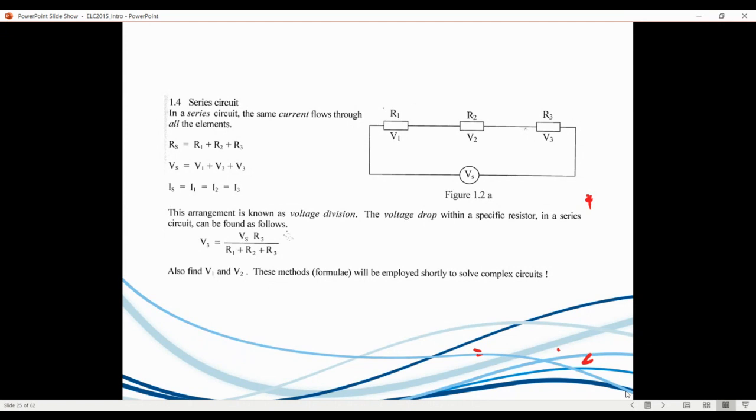For instance, if you have a source voltage there, and then of course that is supplying a current through those resistors. And if you quickly want to find the voltage across whichever individual resistor, you have to take the source times the resistor that you want, and then divide that by the total amount of resistors. So that's just voltage division. We will be doing current division after this.